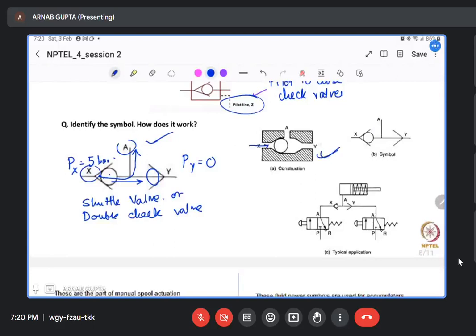Very simple, but very essential, because this fitting should be a very close fit. You can't keep much tolerance here, and the dimensional tolerance is very low, and it should closely fit to the tolerances, because if there is a little bit of inaccuracy or mismatch, the liquid will leak out, and the valve won't be working as desired.